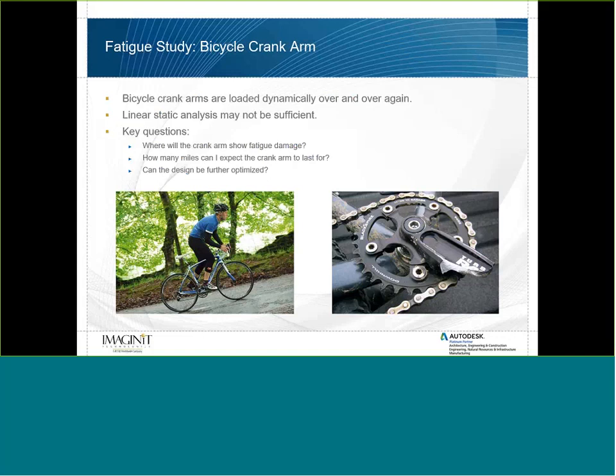that may not really be sufficient. We want to know, well, this thing is going to be constantly loaded over and over again as someone goes on a bike ride. And so it's really a dynamic environment that will require some level of fatigue analysis. The things we're trying to gather here are: are we going to be seeing a significant amount of fatigue damage? At what number of cycles will we see fatigue occur? And where can we expect to see some damage or failure?